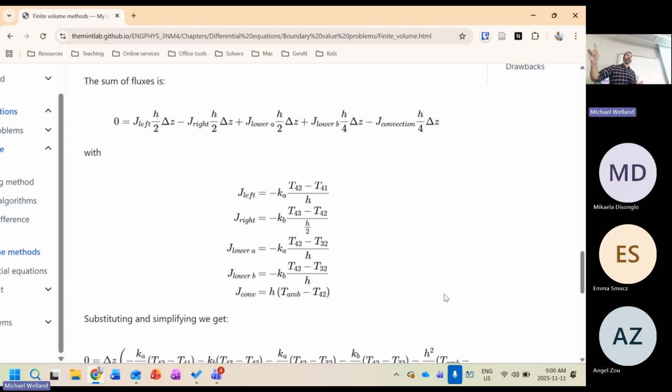Even though, so in COMSOL, what we would try and do is say that your heat flux at the surface is equal to, let's say, J, T minus T amb, right? Just flip the sign, times H. And this is going to be equal to your thermal conductivity times grad T at that point.